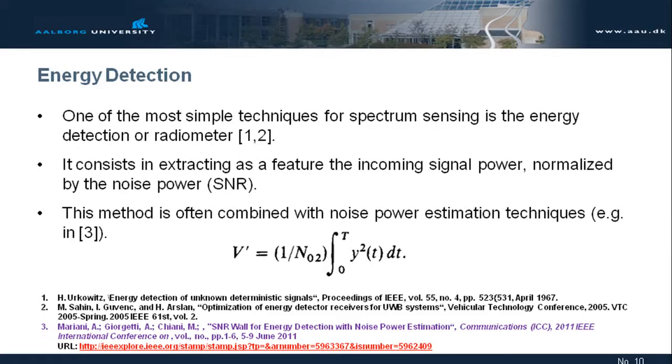You have papers there, and I try to put the old one from Urkowitz, the original one, where this formula is extracted from. But also a couple of new papers that are using this methodology. The latest one is from a colleague and a friend, Andrea Giorgetti, and they are using energy detection and improving it, doing noise power estimation, because now the problem is also detecting in real time which is the real noise power, because we cannot assume anymore that it is the same amount.